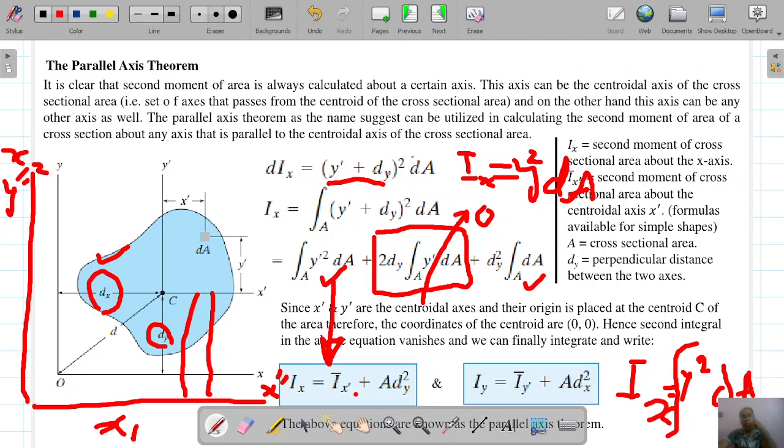I hope you understand the parallel axis theorem and the second moment of area in very simple terms. And just to understand another important point, take your steel ruler, the one you draw a line with. If you hold it parallel to the table it is lying on, and try to bend it by holding its two ends with your hands, you can bend it very easily. But if on that same table you make the ruler perpendicular to the table, and hold it with both hands and try to bend it,